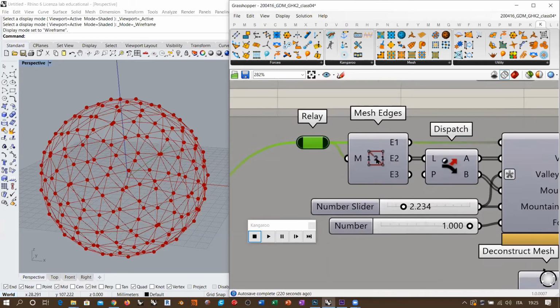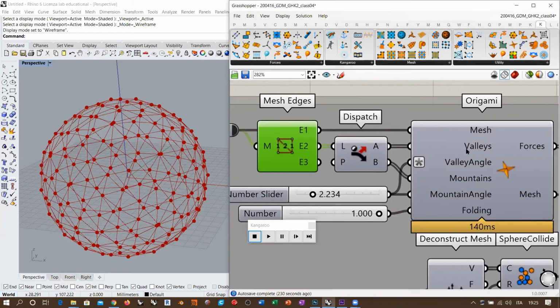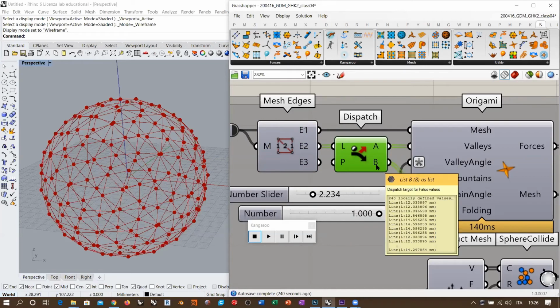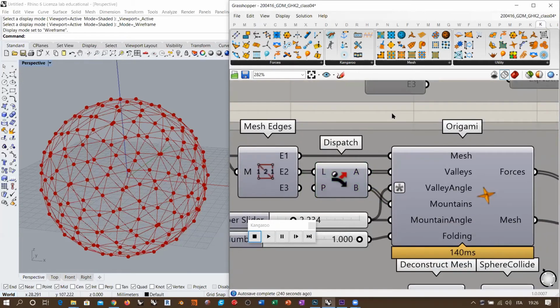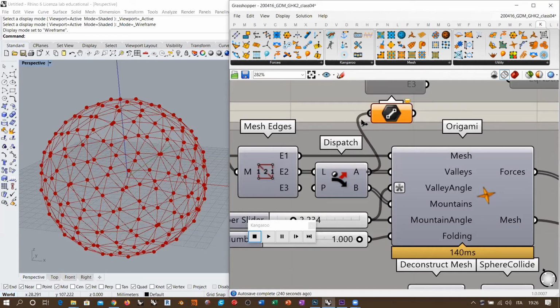So what I did here was create all the mesh edges, use all the inner edges, but in order to divide them between valleys and mountains, I used a generic criteria, which was simply dispatching them with a true-false pattern. So we have here an amount of 480. I get 240 here and 240 here. The thing is that these lines are basically grouped randomly.